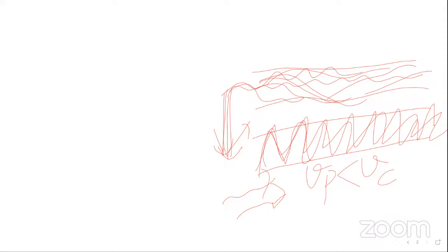To solve this problem, what am I using? I am sending the wave in the waveguide in a zigzag fashion. If I send the wave in zigzag fashion, it bounces off the walls and travels again up to the end. The electric field is maximum near the center. Across the walls, the field is 0.